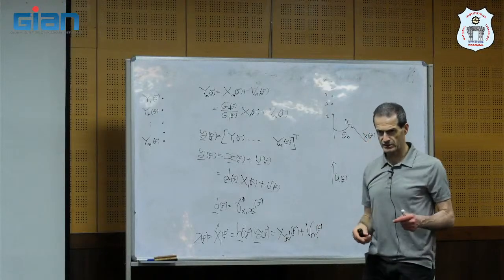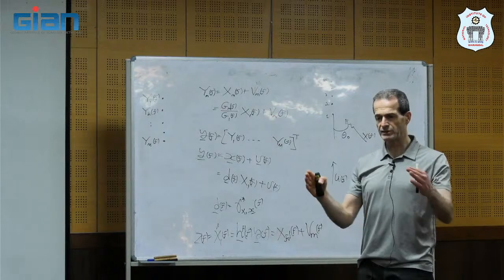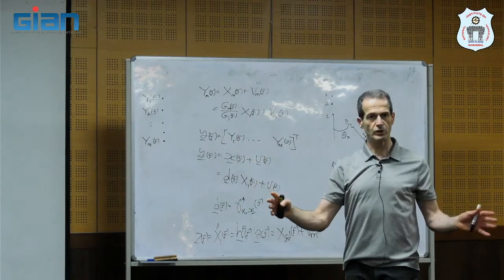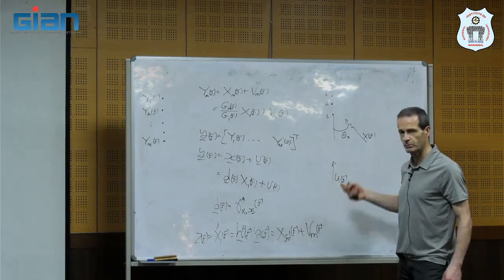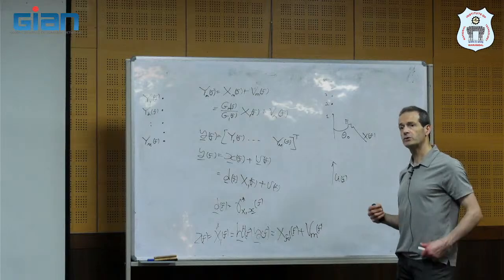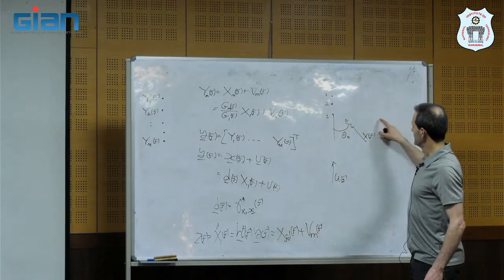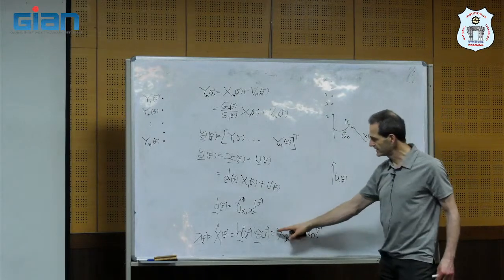So if we use a certain number of sensors, and then we have a certain beam width, and we also have side lobes, which means how much we can reduce these noise components.